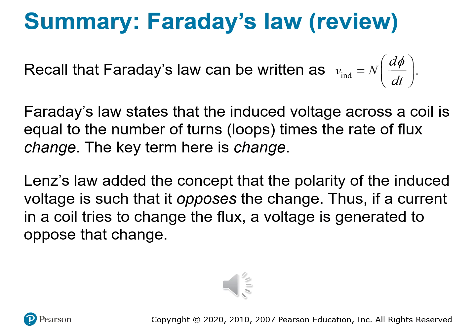All right, so anyway, this law is the heart of electromagnetic induction. It's V_ind equals N times delta phi over delta t. V sub IND is the induced voltage. N, again, the capital N is the number of turns in the coil.